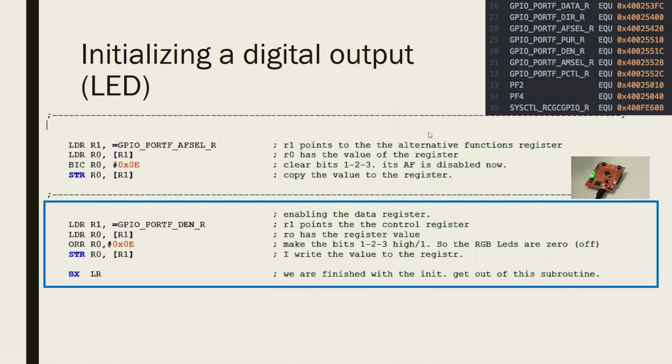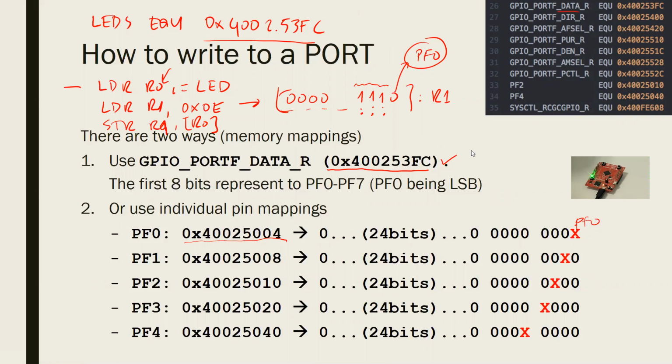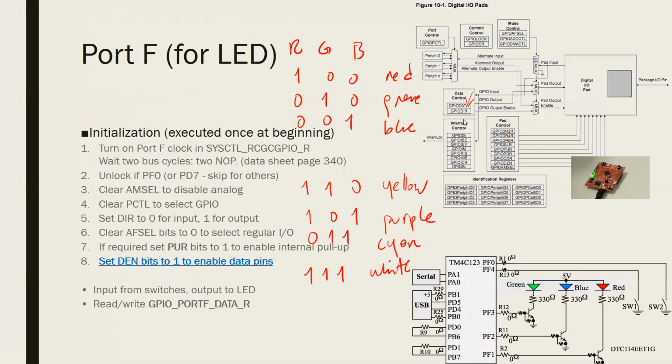Good question. Your friend is asking, will the LEDs shine or not according to the values that we put in this address, which points to the port F data register, which is this register here? The answer is yes. We can generalize this yes. The purpose of this port is that there are 8 pins to use as input and output, right?